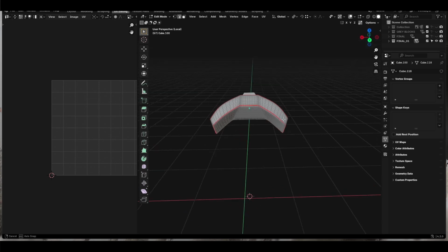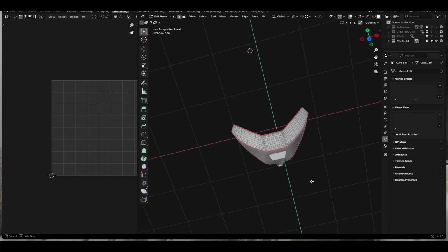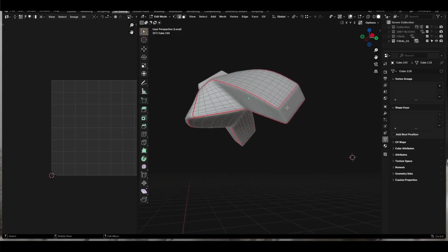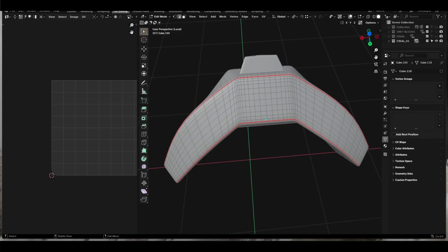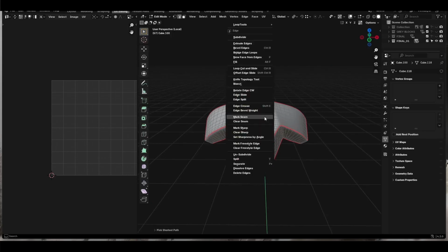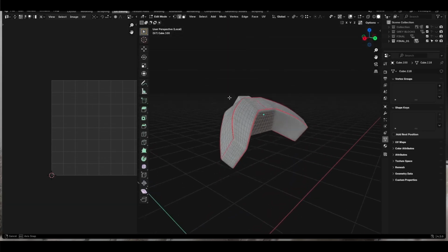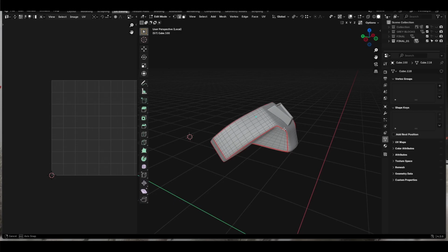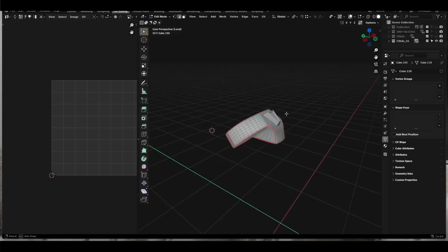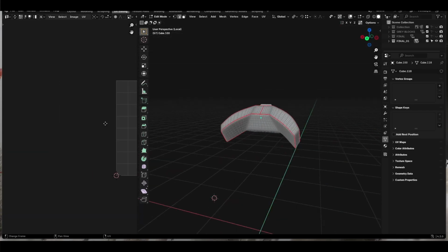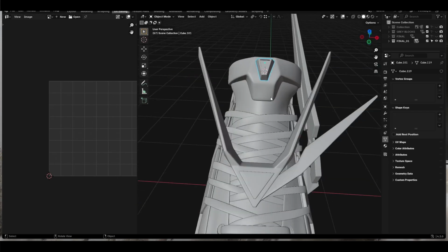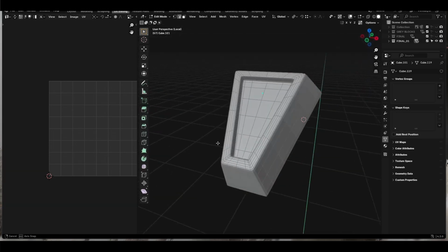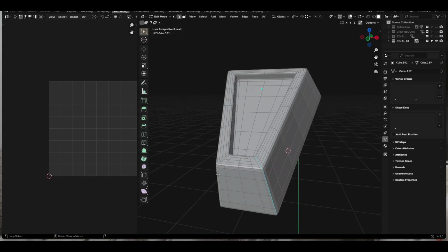This part will be 1 island as well, but it needs to be cut. I need to cut them into half. I think I'm gonna create a cut here. So mark seam. Okay, so this part will be divided into 2. Then the overall UV will be divided into 3 islands. Okay. Next is this one. This one's a little bit easy. Like, can use the box method.